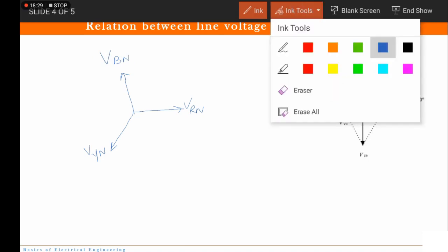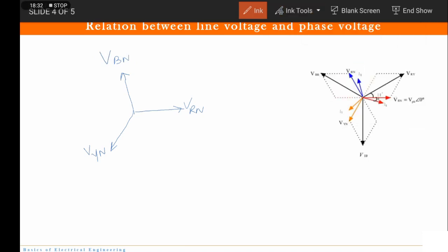Now the second thing is going to be current. I will assume the load to be inductive, which is normally the case. If the load is inductive, it has some resistance also. So it lags behind the voltage by phi. But why is this not 90 degrees? Because the inductor will not be a pure inductor, so it has some resistance and lags by some phase, which is phi.